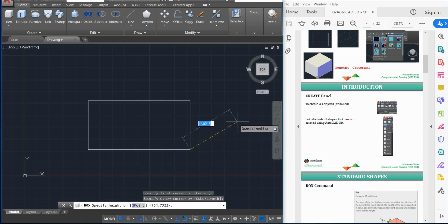As I said, to build a box, we should build a base of rectangular shape, then we're gonna extend it with a specific height. Then you can type the height value. We can give a height, for example, like 800 and press enter. So as you can see, the cursor had been converted to the default shape, like 2 intersecting lines, and there is one box in the middle.